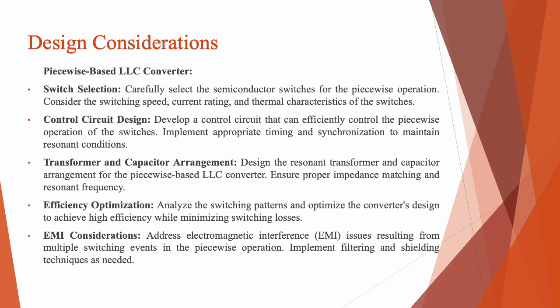The second one, the control circuit design. We have to develop a control circuit that can efficiently control the piecewise operation of the switches, and implement appropriate timing and synchronization to maintain resonant condition. The third one, the transformer and the capacitor arrangement. Design the resonant transformer and capacitor arrangement for the piecewise based LLC converter. Ensure proper impedance matching and resonant frequency.